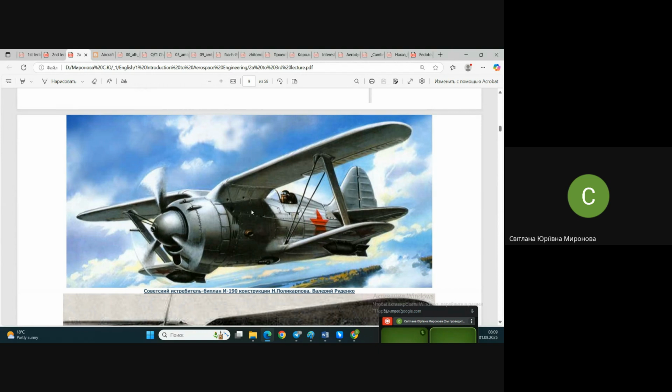There are decisions where they join it immediately to the fuselage with reinforced frames. There are such decisions, but they are not convenient. They're even heavier and more complex technically. The airplane will be less in weight where the spars from one side and the other side meet each other somewhere here, either as an immediate meeting of left and right halves in the structure, or as a so-called center wing, which is actually the same wing but hidden inside the fuselage.